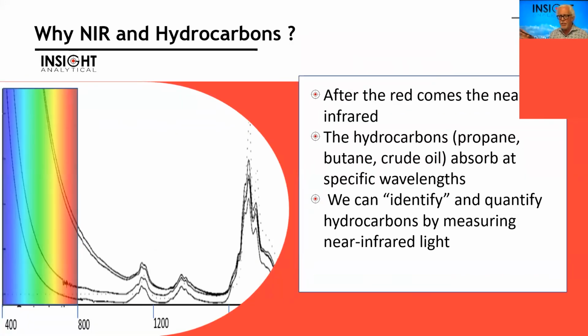So why do we use near-infrared spectroscopy? Why that for hydrocarbon analysis? If you look at crudes or condis that are dark and black like this, you can say, well, there's no possible way you're going to use light to measure anything in this sample because they're very opaque. What this chart is showing is that these materials absorb a lot of visible light. That's why they're dark. But as we move beyond the visible, beyond the red, and into the infrared, they stop absorbing so much light, and you can get a beam of light to shine right through it in the near infrared